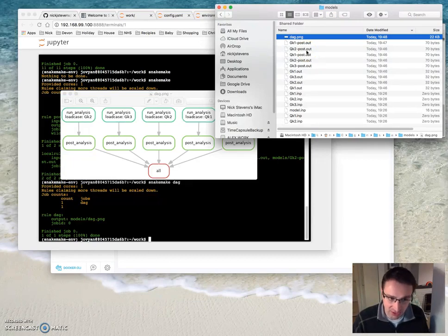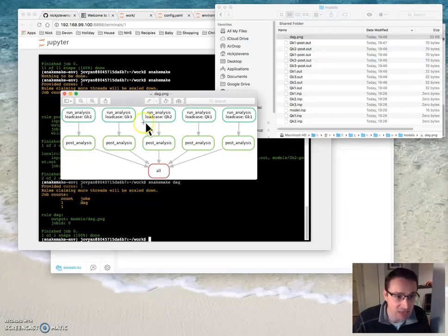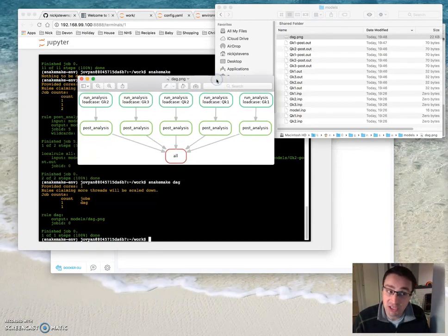So you could bring all this together, output results to CSV files, have scripts to process it, and then use that to write a report in Markdown at the end of it, so that the entire workflow from model creation, running, post-processing, and reporting is all contained within a pipeline. You can be sure the dependencies are all valid and everything's up to date, and that when something does change, you need to update the report if a particular file changes.